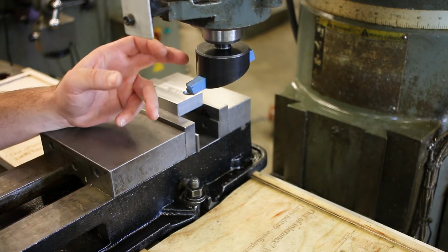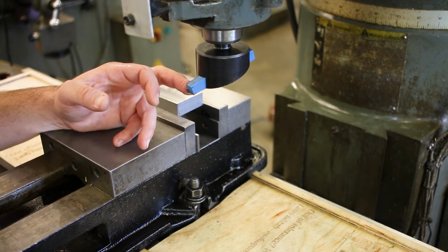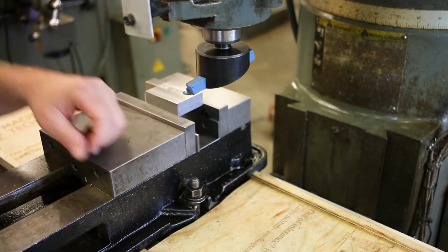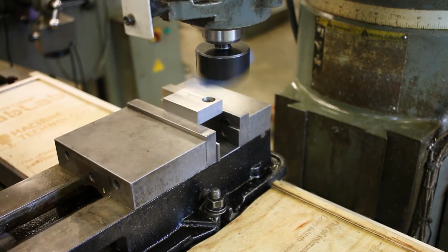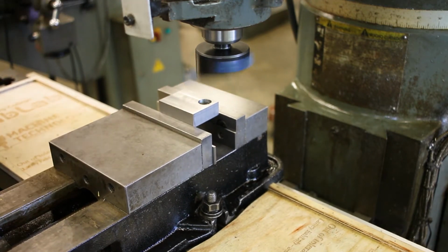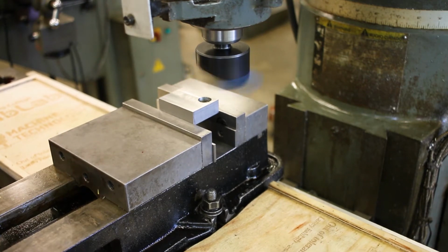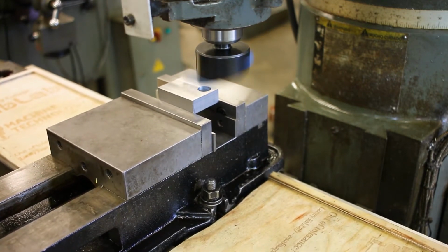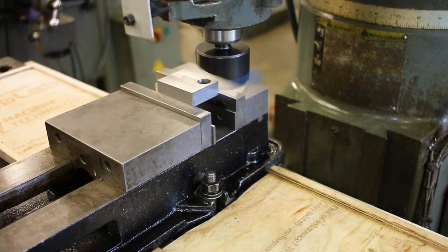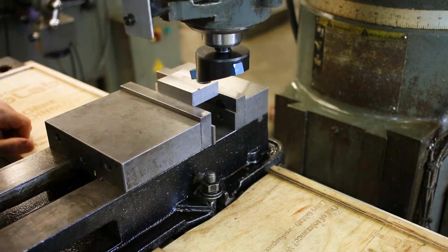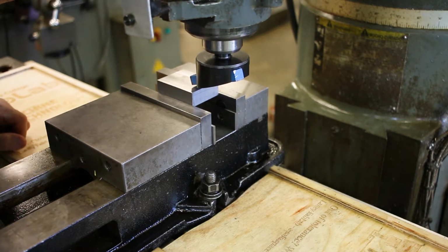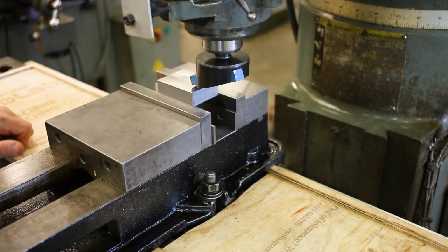Because these cutters only have one cutting edge, I always do a dynamic touch-off with these. So let me go ahead and start this thing up. Okay, I'm going to go ahead and position this about center of the part so we can take everything in one go. Raise the knee a little. Actually, let me go ahead and bring this a little bit closer with the quill. There we go, just so I'm not moving the knee quite so much.